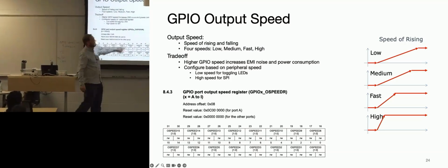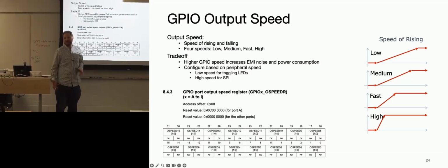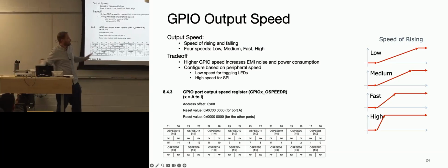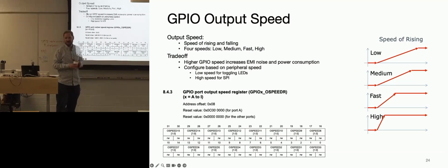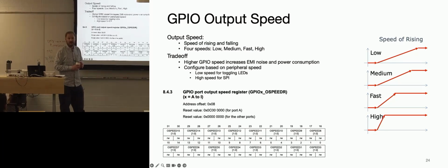Why would you want to have different speeds for your GPIO pins? What does different speeds even mean? The frequency in which you'd be receiving data. Well, this is for drive strength. This is all about driving. Anybody else know why you'd want to control it? Power consumption. If you can't afford high power. That's a good one.